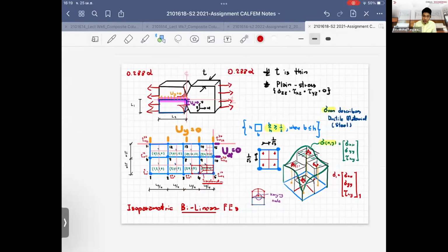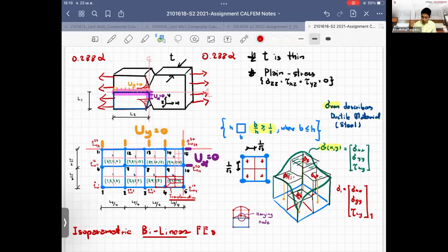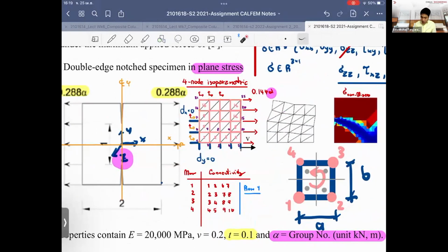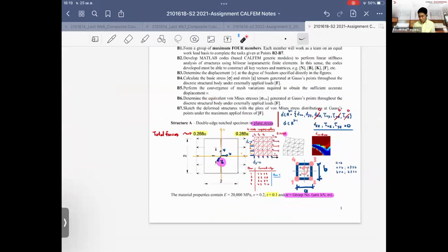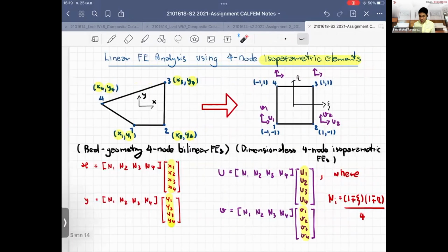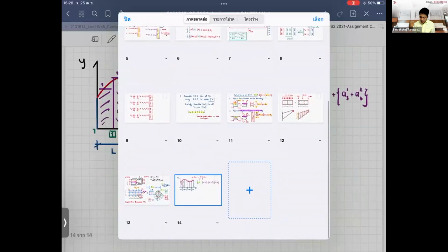So if we're looking at our problems, what I suggest to you is that in this case, because it's quite simple, you can just try and subdivide the element by using the uniform discretizations. So you might start from the 4 and you subdivide them to be 16, and you times 4 again until you get the more accurate results. And how do you know that you should stop the structural discretization is as follows.